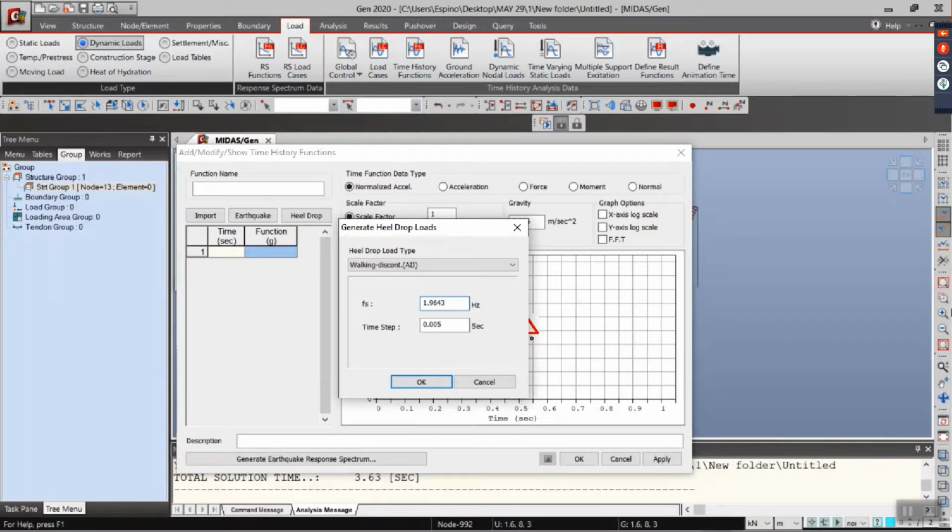The normal frequency of pedestrians ranges around 1.6 to 2.5 hertz. If I take a frequency of, let's say, 2 here, multiplying 2 by 2 is 4. If I multiply it by 2, it means that the frequency matches every 2 steps. So I can use either 2 or 4 because the frequency of the steps will coincide.